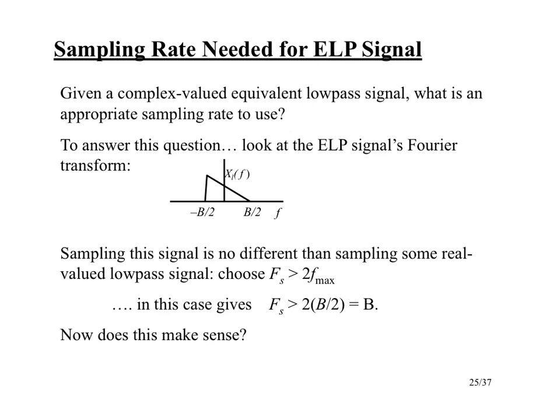Remember, we talked about taking our RF signal and putting it into some sort of analog circuitry that generates the I and the Q. So here's our I part, here's our Q part. And we saw what that box would consist of: a splitter, two mixers, an oscillator with a phase shifter to create the 90 degrees phase shift, and two low-pass filters.